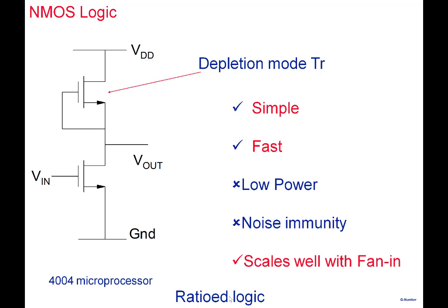It's a ratioed logic. The output value here, the output load depends on the size here and the size here. It's a ratioed logic here. All right, so at least 2 of the disadvantages have been eliminated by going towards this kind. But note that a separate disadvantage comes because in my fabrication process, I need to construct another kind of a transistor, which is a depletion mode.